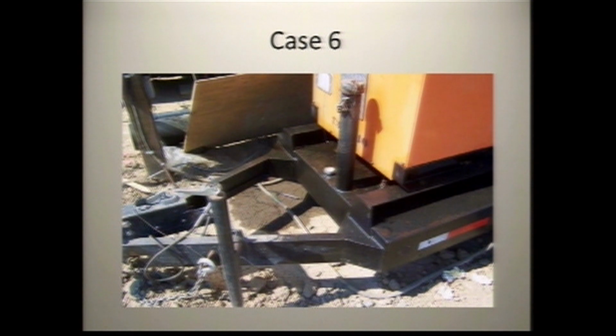How about here? Yeah, fuel spill. All right, it's an auxiliary power unit. It's diesel. It's on the ground. It needs to be cleaned up, and the proper way to clean that up is dig it out, goes into a hazardous material drum, gets the licensed hauler to take it off site.